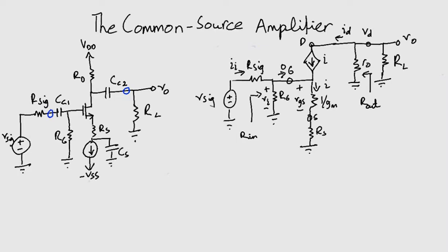Notice that we have not included R0. In this particular case, R0 would have made the amplifier non-unilateral. However, the effect of R0 on the operation of this discrete circuit amplifier is not important. So we start our analysis again. Rn again equals Rg. We write the equation for Vi. However, Vi this time is not equal to VGS.